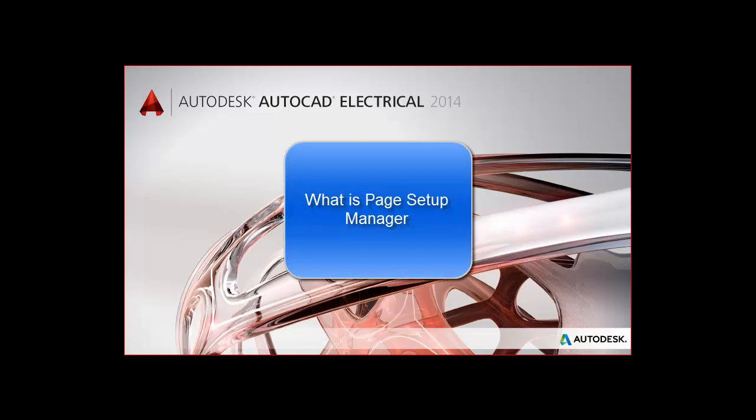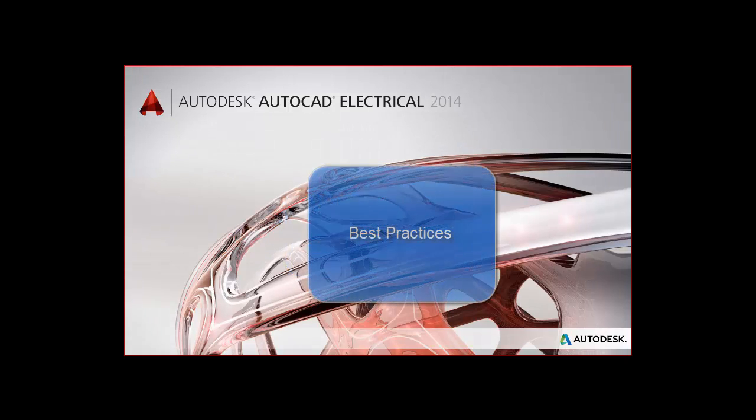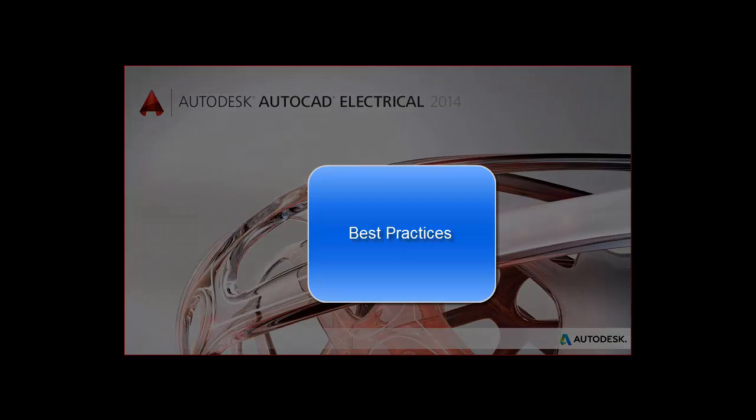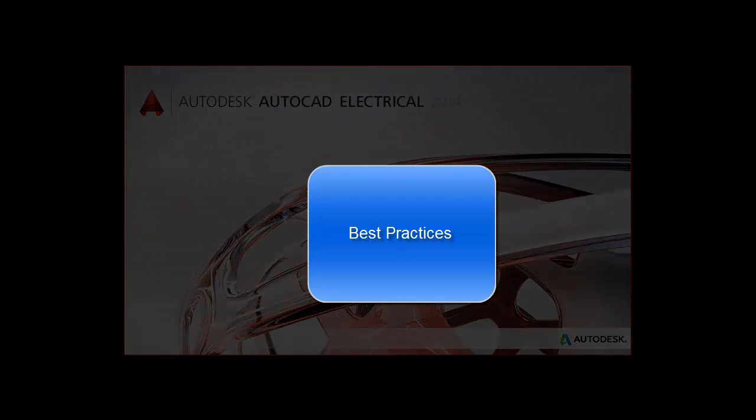Page Setup Manager is the tool you use to create layout or paper space configurations tailored to specific printers and borders. Page setup configurations are also used when plotting or publishing in the background. How this works is covered in a different tutorial. It is a best practice to create a local default drawing to create and store page setups in for import into new drawings.